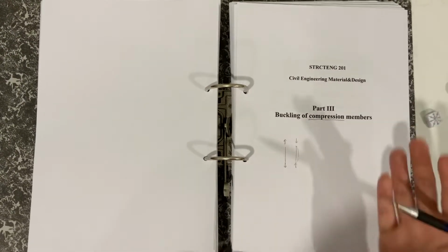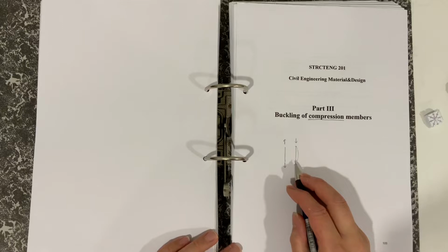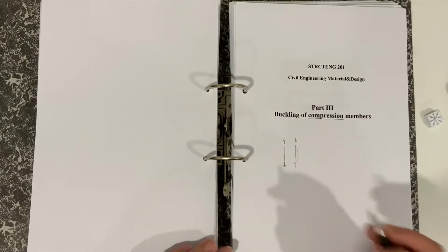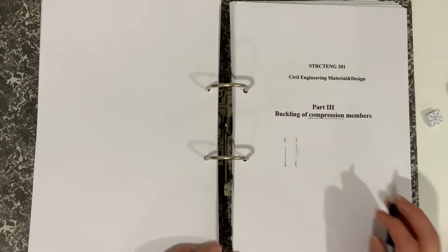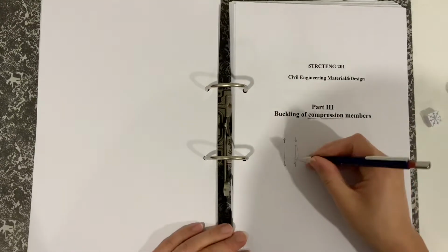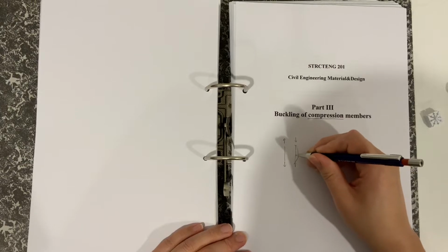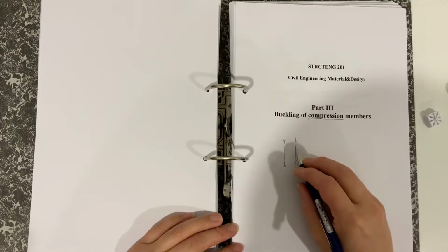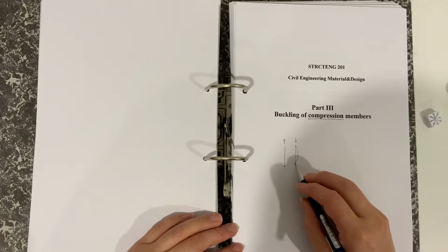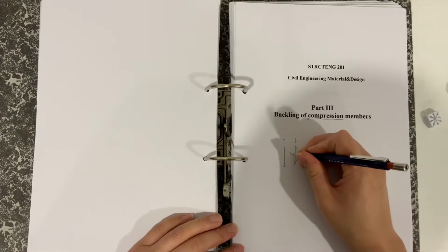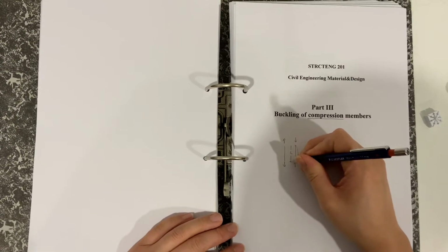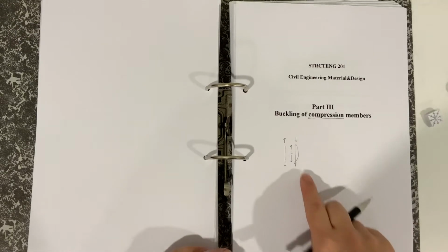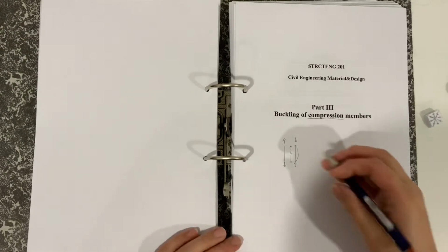The way it would choose to buckle is based on some impurities in the material or something that makes it more susceptible to go to one side or the other. But it really makes no difference at all when it comes to the mathematics. And as I mentioned, we call that a half sine wave, buckling over the length L, because that would be the length of the beam or length of the column. So L would become your half sine wave.